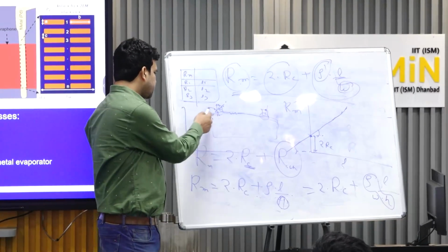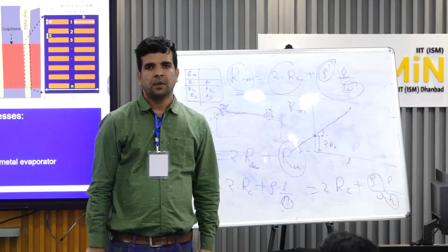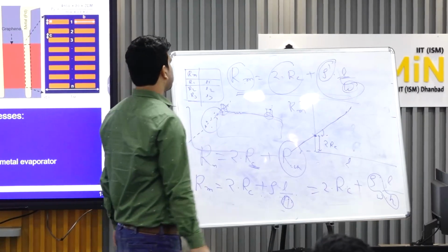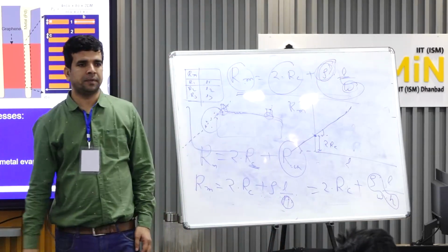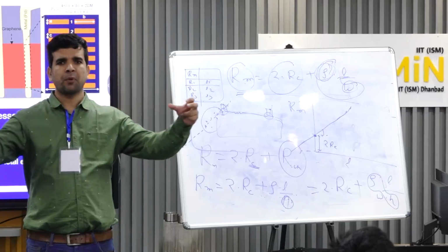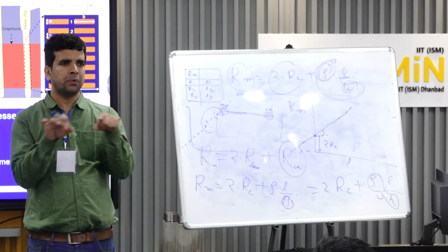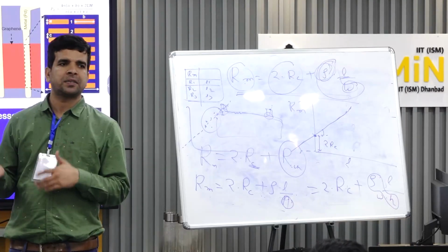Why is there this deviation? Ideally, it should not deviate. Ideally, all the points should follow the same line. But the deviation is there because we have assumed that resistivity is also constant. Resistivity is a material's internal property, but a 2D material has a lot of defects. Whatever material you get, you will not get a single crystal. Somewhere you can find more defects, somewhere less.